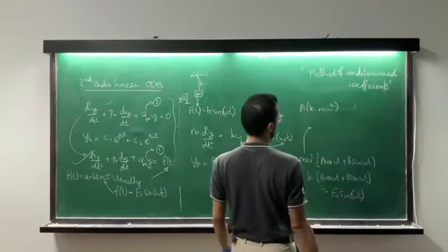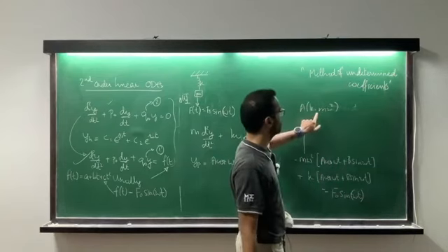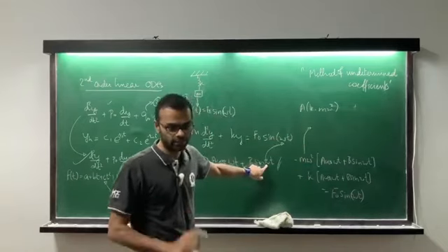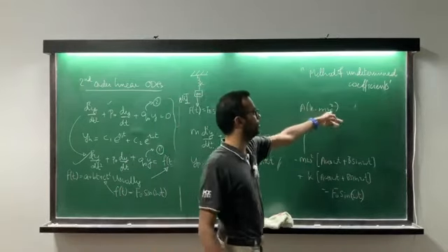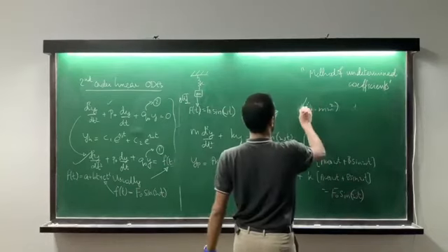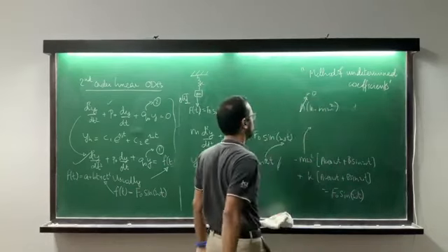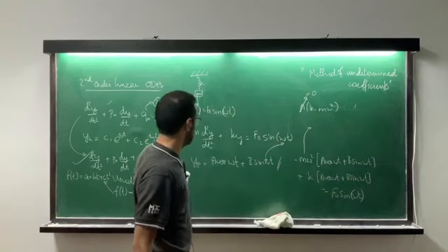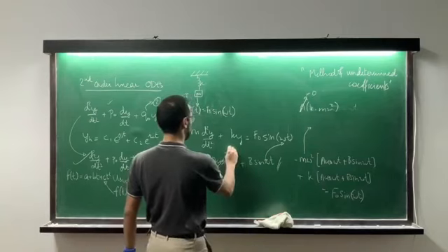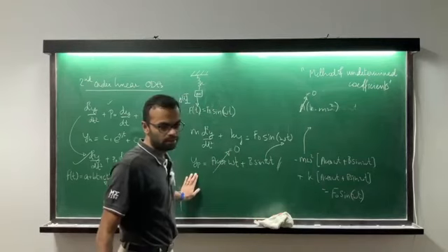There is no reason why m omega square must be equal to k. Remember, omega is the forcing frequency, not the natural frequency. So there is absolutely no reason why omega should be equal to square root of k by m. So the natural consequence is that a equals 0. Okay. So a is 0. So this term does not exist in the particular solution.